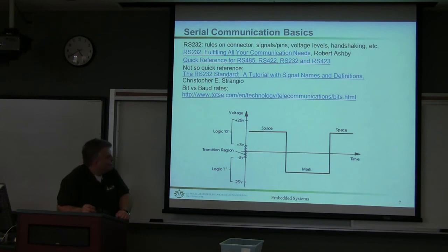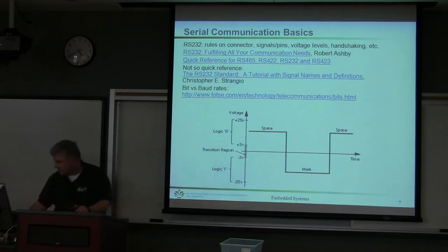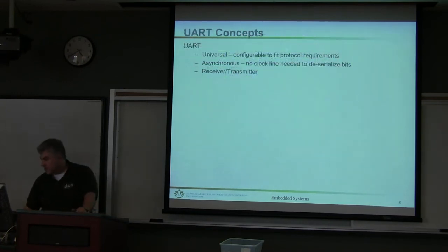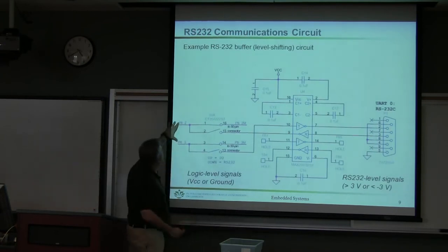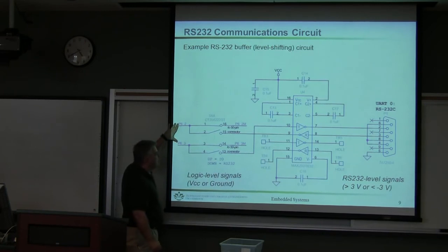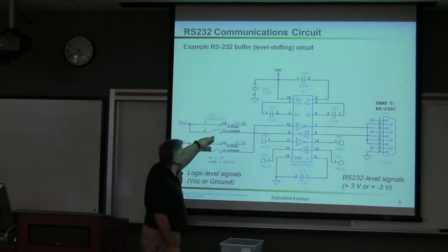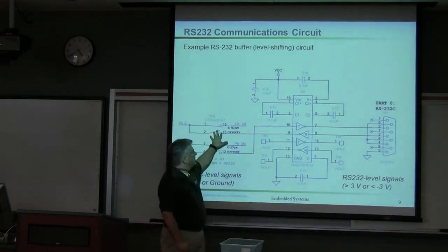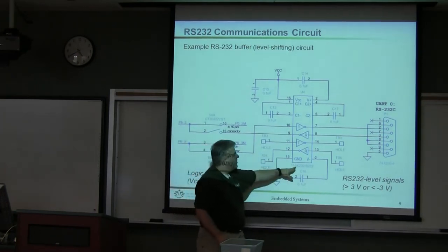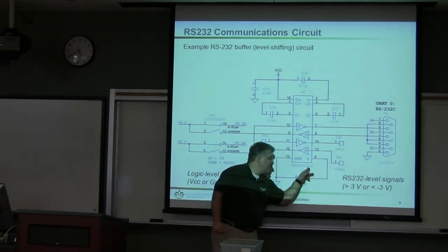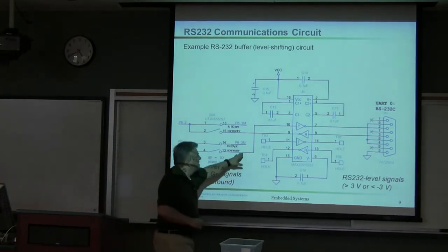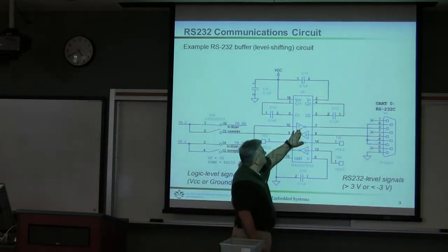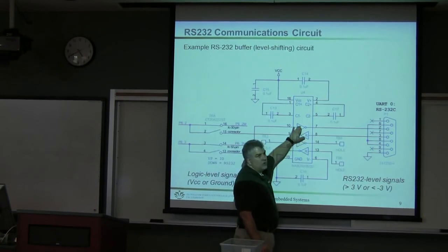Now keep in mind, what you're going to see is really something like this. You have your processor chip over here, and in this case, let's say we'll connect a little jumper pin. And you have this chip over here called a Maxim 232. It will take a transmit signal. It will adjust the voltage.